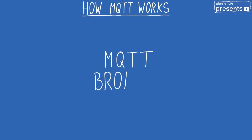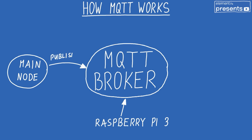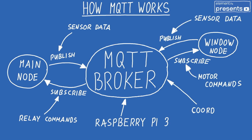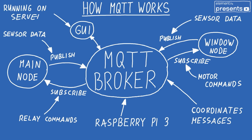So how does MQTT actually work? In the center we have the MQTT broker, which actually coordinates all of the messages. We have topics which are channels on which we communicate, and we can either publish or subscribe to them. If we publish, we send data over them, or if we subscribe, we read the data coming from the broker. So for example, we publish sensor data and we subscribe to commands coming from the graphical interface and things like that. So that's a short version of how MQTT works and how that previous experiment worked.